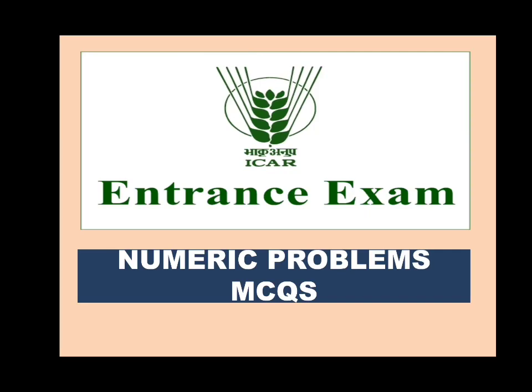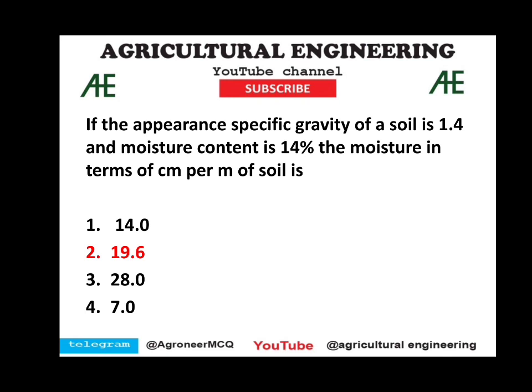Numerical problem: if the apparent specific gravity of a soil is 1.4 and the moisture content is 14%, the moisture in terms of centimeter per meter of soil is. For finding moisture content in centimeter per meter, if you are given specific gravity and moisture content, you just have to multiply the moisture content by the given specific gravity. Here moisture content is 14%, so you just consider 14 and multiply by the specific gravity, which is 1.4. You will get the answer 19.6.